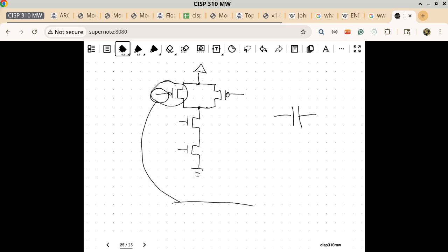Physics says that copper wire, on your circuit board or inside the processor, is not perfect in the sense that whatever voltage you present on one side is immediately on the other side. So every wire has two internal components: a resistive component and an inductive component.